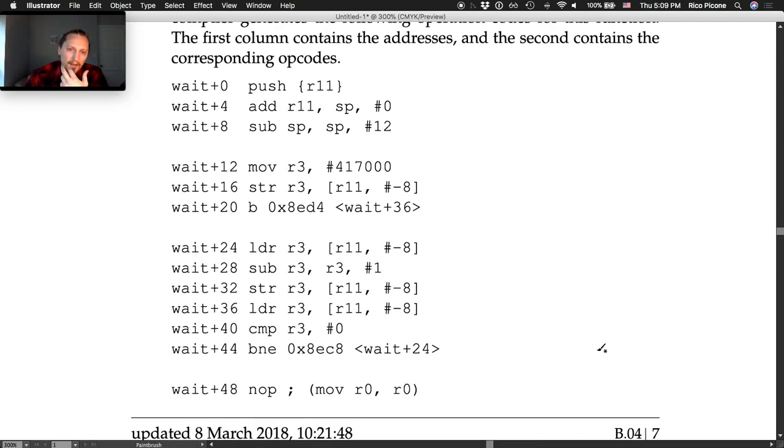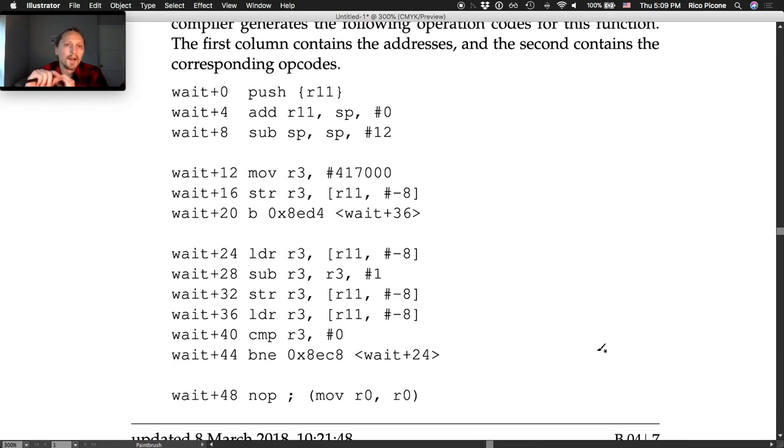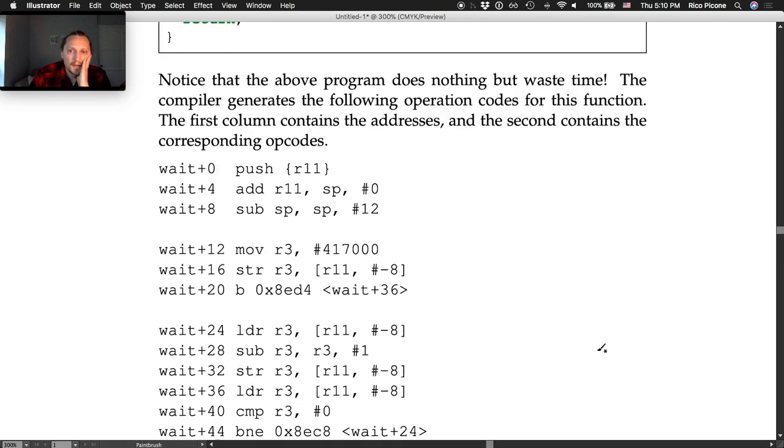I wanted to talk for just a minute about calculating by just adding up the opcode number of cycles and the cycle time given the speed of the processor, inferring the real time from our wait functions' opcodes. So I give a reference here.